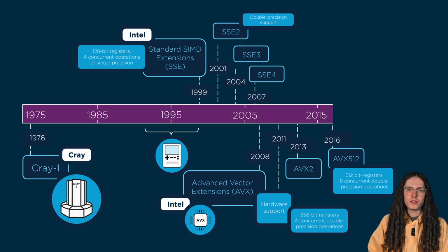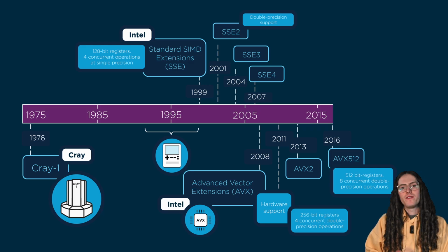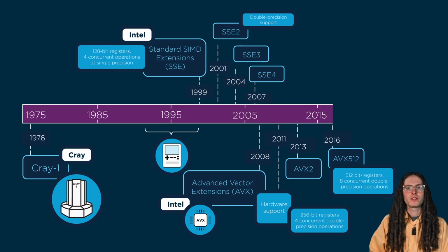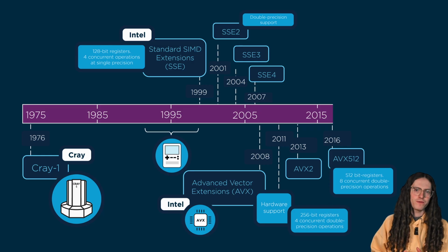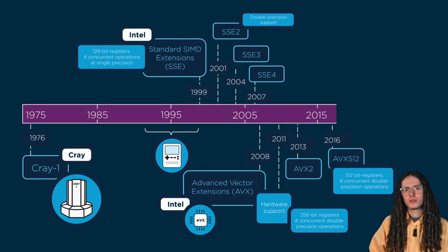Though vector compute units have gained functionality through larger registers, challenges remain. For example, they typically run at reduced clock speeds. The actual hardware produces substantially more heat than the typical ALU due to the dense packing of the compute units and focus on computation primarily in that region of the silicon. When the vector units run very hot, the computer downclocks the CPU, and this behavior has led to some underwhelming implementations of vector computing in the past. Therefore, the performance of vector compute units can face a tension between their increased throughput but reduced speed.